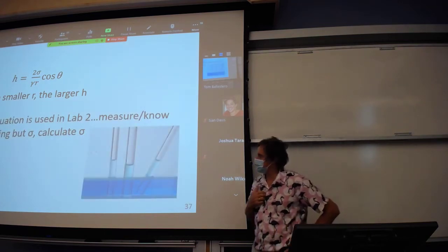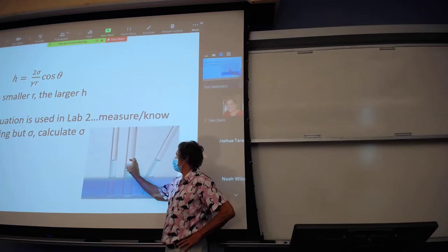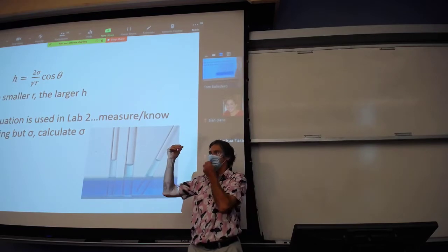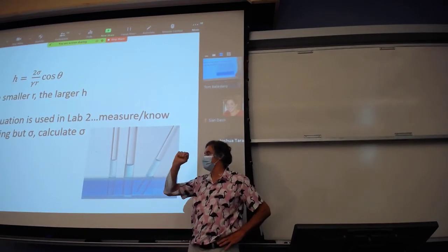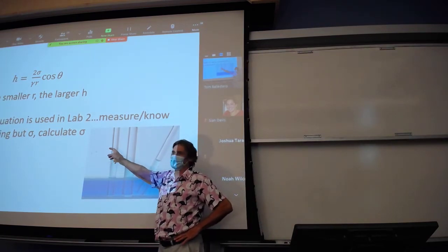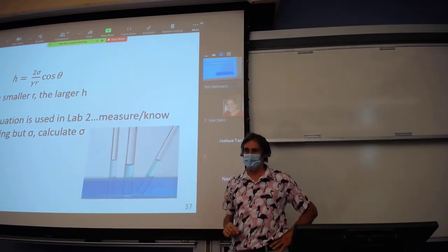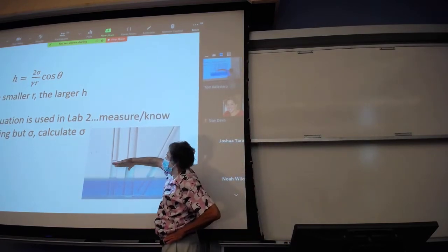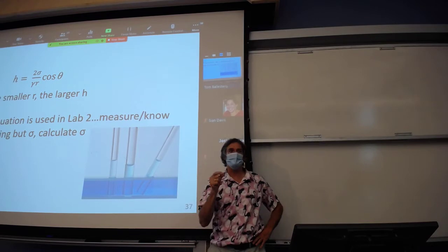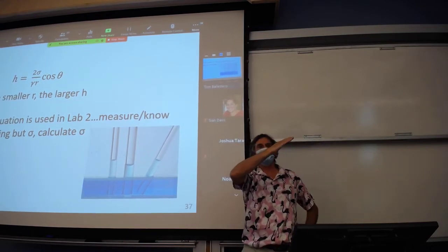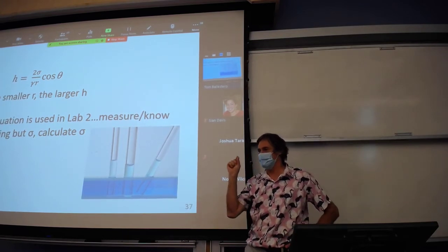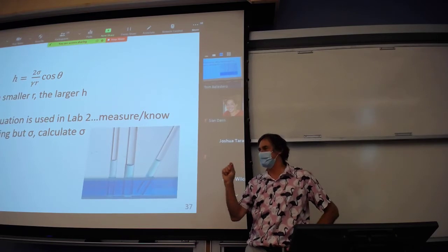So we talked about this. And so in this figure, what you see is a large diameter compared to a small diameter. And you can see how the capillary rise changes consistent with that equation. The other thing you see is the capillary tube on the left and the right are the same diameter. The height of capillary rise is the same. The vertical dimension is the same. The length that's in the capillary tube is different because on the rightmost one, it's at an inclined angle. So again, the height of capillary rise is a vertical dimension. Why? Because we looked at a vertical analysis of the system.